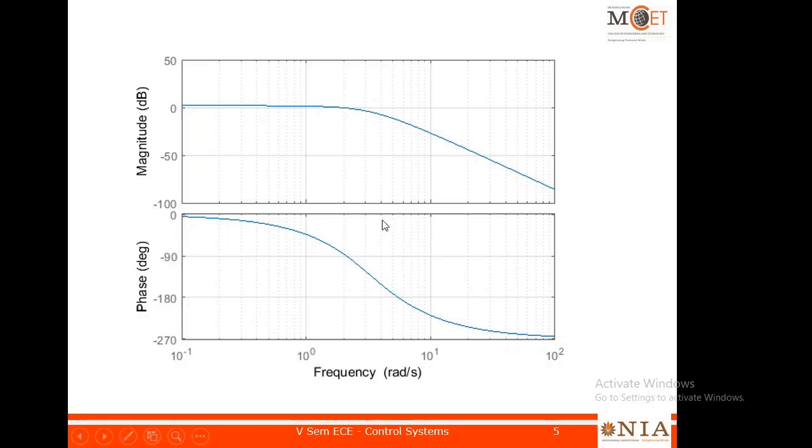For your information, this is not the only way of drawing a frequency response curve. This is one of the ways of drawing it. So this better explains what is meant by frequency response, so I have used this. There are other ways to draw frequency response curves also. This one is the most simple, that is, you draw in a semi-log graph sheet the magnitude of the transfer function in decibels versus log frequency, log of omega, and phase versus frequency.